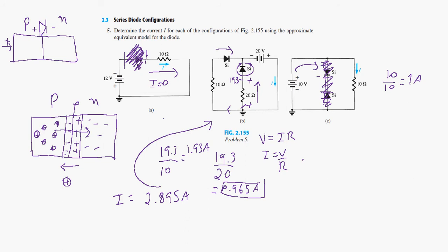Very little of these charges will fly here. So we need a positive voltage on here and a negative voltage on here, and when we do this, we have a voltage here. This voltage will create an electric field in this direction, which has to be larger than this electric field, and therefore that's why we have the 0.7 volts drop here. And after that, we destroy this depletion region and charges can flow. So that's the diode. So let's go on to the next problems.